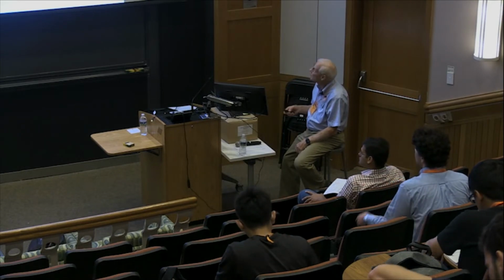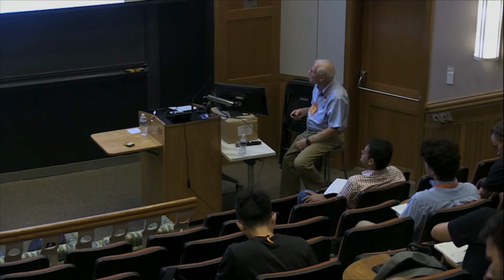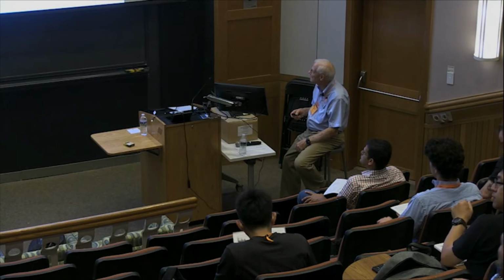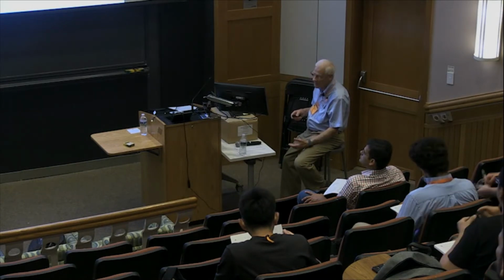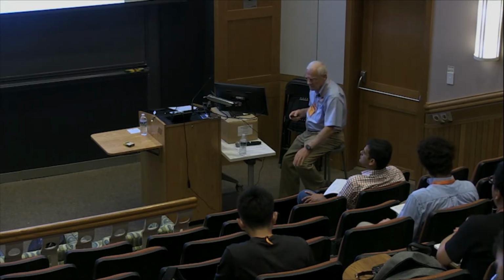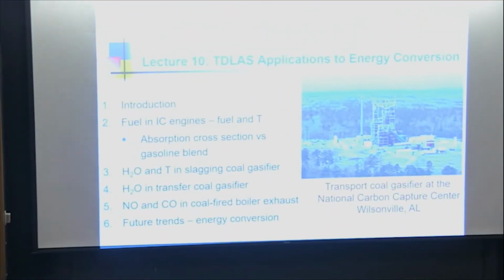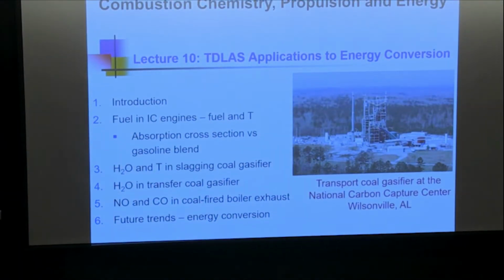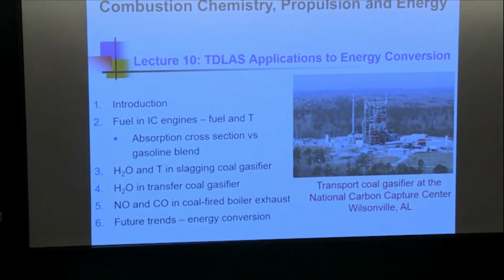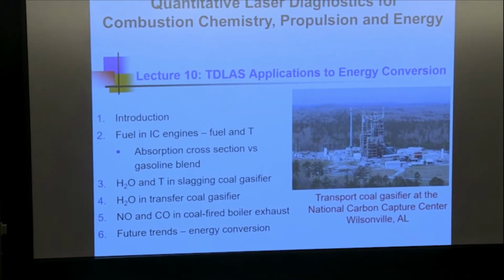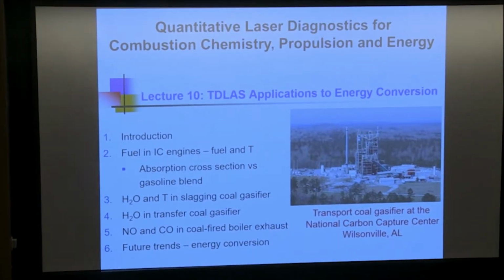This is a picture of what's called the National Carbon Capture Center, NCCC, in Alabama. It's a big thing. It's not full scale. It's a kind of prototype coal gasifier. Coal gasifier means you take coal and you're trying to make syngas, hydrogen and CO, and you do that by bringing in the coal and basically combining it with hot water, steam.